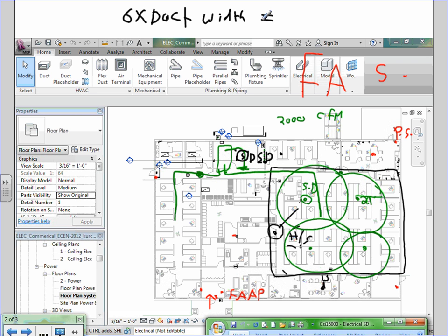For this particular design, you don't really need to worry about that, but I want to make sure you're aware of that, because the return duct is only in the mechanical room, and depending on where it actually is, you might not actually even be able to get 6 duct widths away from that unit. But you need to keep that in mind, and again, it's only a recommendation by the manufacturer. It's not a code.